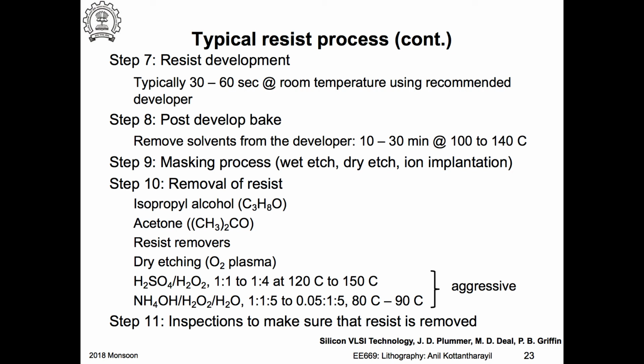A lot of these inspections can be done using very simple microscopes. If you go to the CNL lab, we have a microscope that can give you a resolution of 1 micron. Features can actually be seen. For most of the applications, that is good enough. You do a good microscopy, it takes you 5 minutes, and that tells you whether you should proceed further with this wafer.